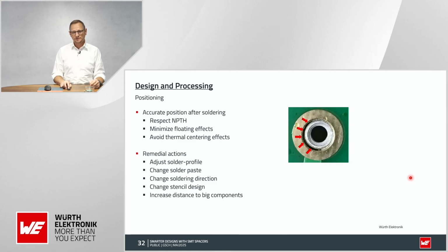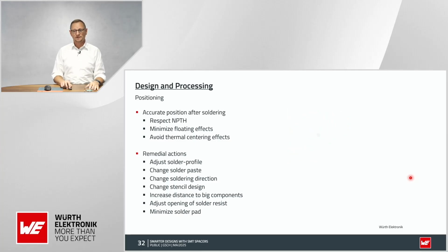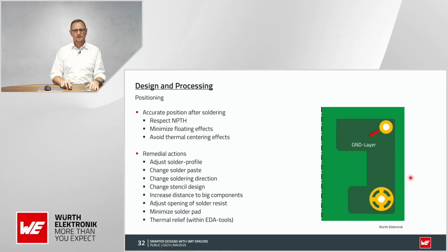Especially you can increase distance to big components, and therefore you reach better heating of the component, and adjust the opening of the solder resist as well. And you can minimize the solder pad. There's a lot of possibilities that you can use.